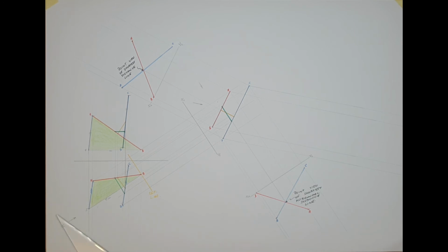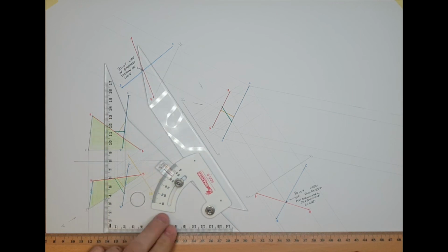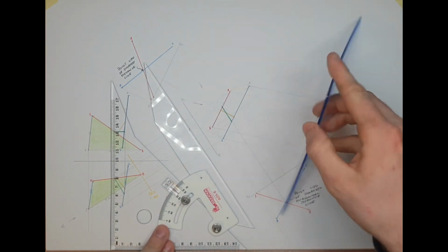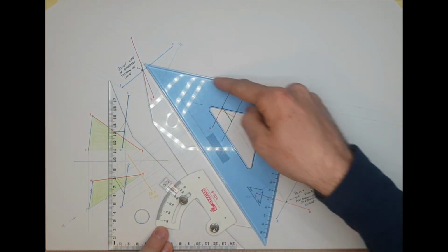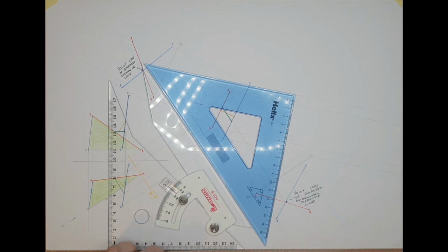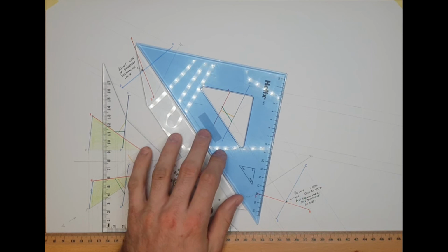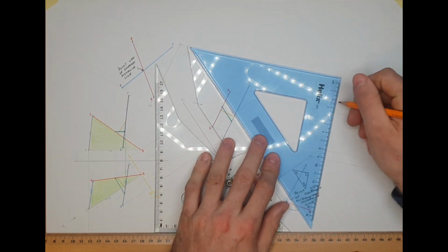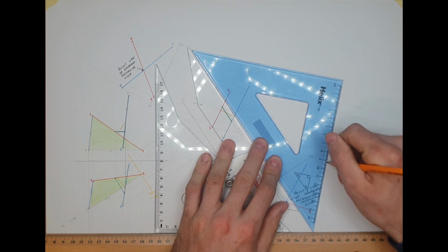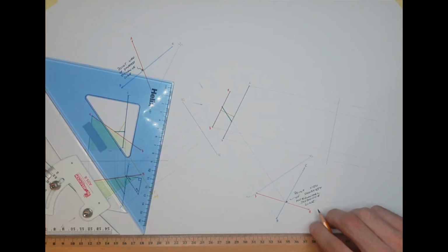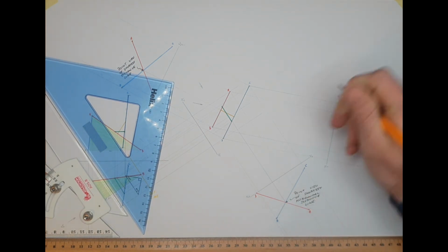And now this guy goes back in again. It's all based on the adjustable this time, of course. If I project it out at 45 degrees, here I'll use the 90-degree corner to set up my next view. I'm going to move out past this one that was down here, and I'm going to drop in my x1, y1. I should say, I was x3 last time, now I've got x4, y4, because it's just another auxiliary view.